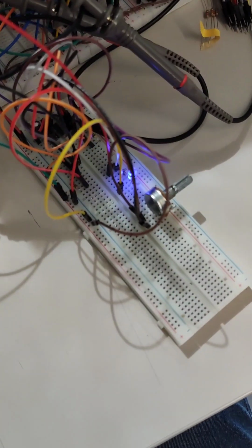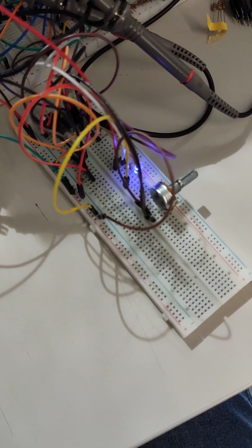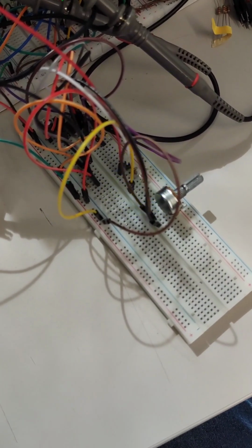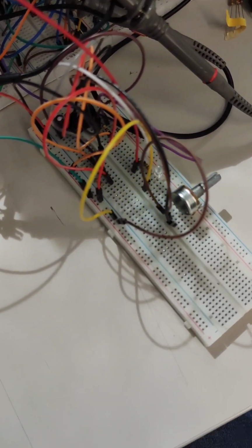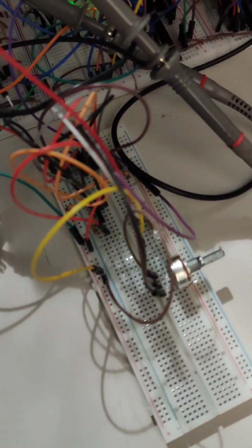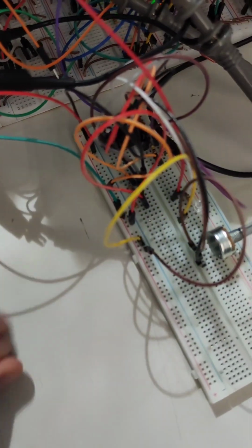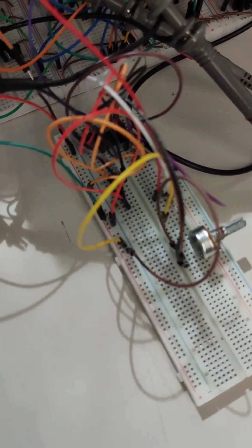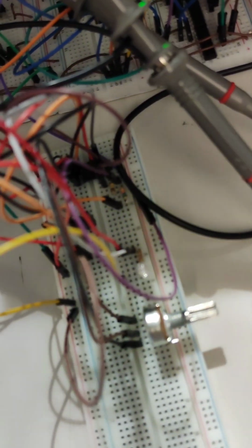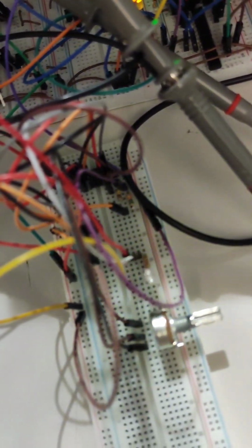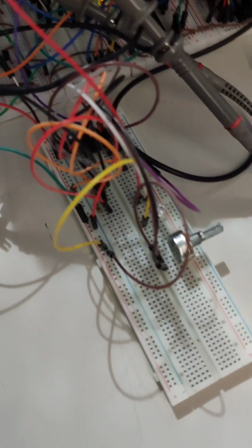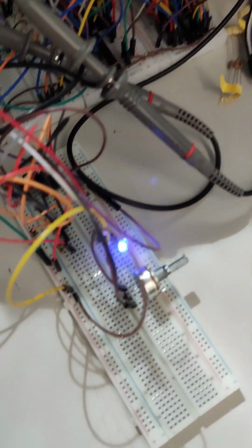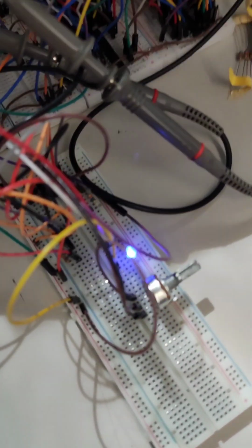That's all. Finally, I will explain the second part of the third task of the project, the duty cycle controller. In this part, as seen, one potentiometer, one NE5532 op-amp integrated circuit, resistors and capacitors are used. In this circuit, the duty cycle changes as the potentiometer is changed.